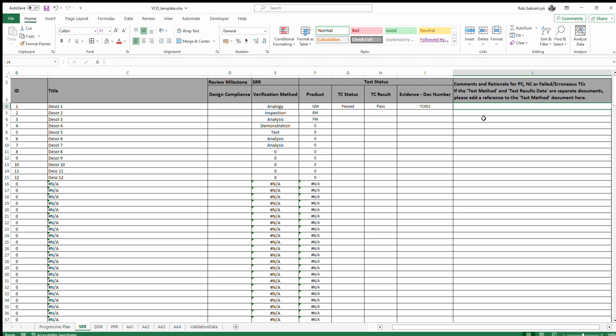And what I mean by that is that it's easy to measure the wrong thing. If you're doing an inspection that constitutes a measurement activity with something like a CMM, it's perfectly plausible that the wrong dimension could be measured. Usually the methodology by which the test is performed, what equipment is used, whether that equipment is up to calibration and has certificates to demonstrate that, all of that information should sit within either a methodology, a procedural document, or a protocol.